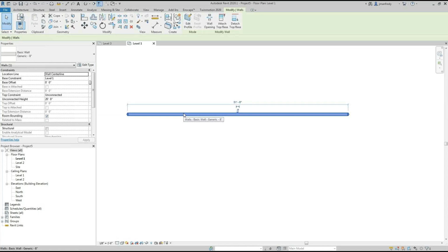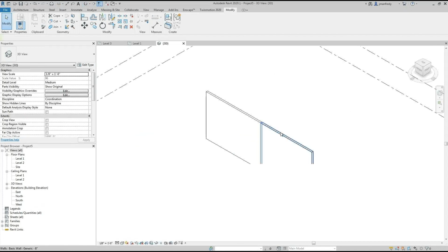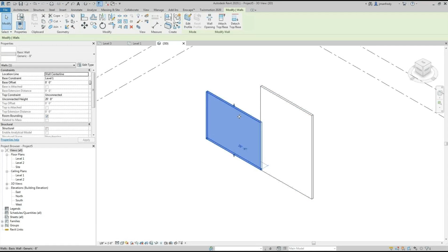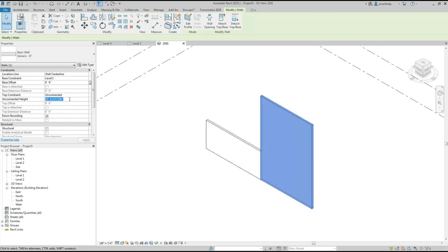So what you do is you click on the wall, and I showed you a line. Move is obvious. Here's right there, it's called Split Element. I can use that command, take the X-Acto, and I cut through the wall. And then what that does, it makes two walls like this, and each one can be independent. See? This one has properties. This one has properties. But they began life as the same continuous wall.